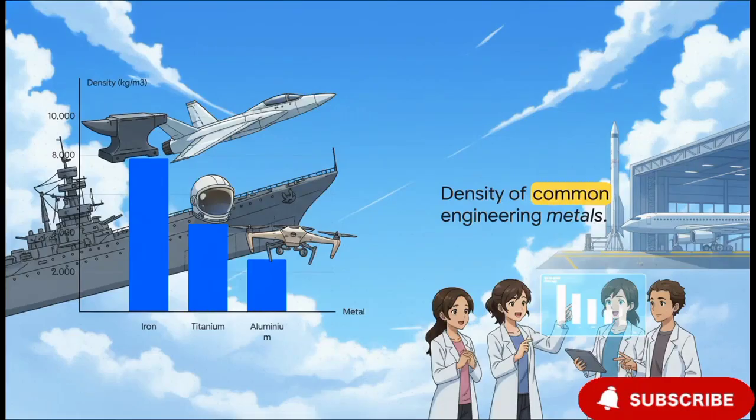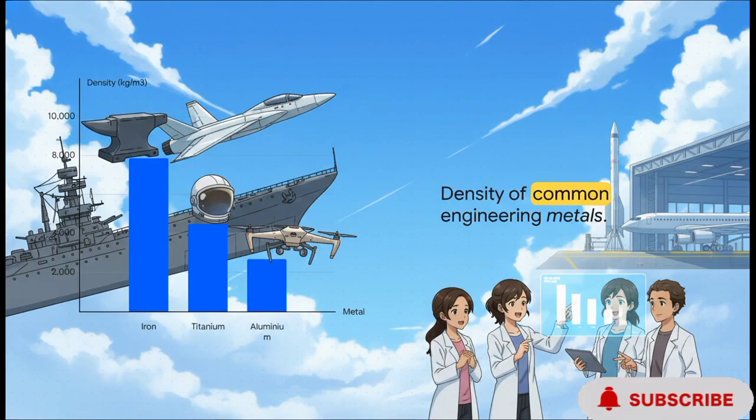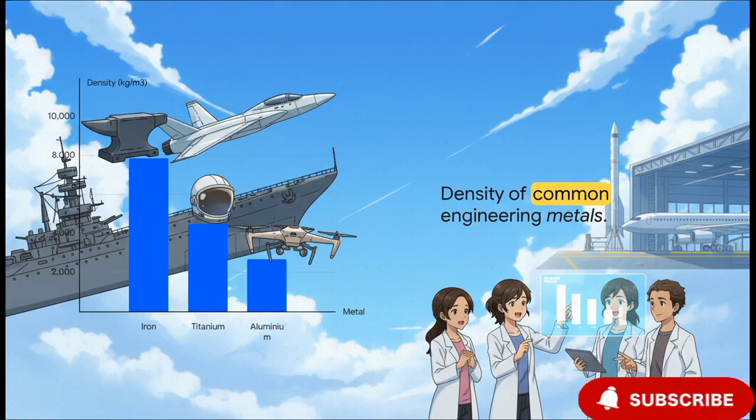Now, obviously, not all metals are created equal. Just think about the sheer difference in density for a second. Iron is incredibly dense, coming in at nearly 7,900 kilograms per cubic meter, but then you have titanium, which is almost half that weight, and aluminum, which is even lighter, at just 2,700. Visualizing this really builds an instant intuition for why aerospace engineers choose specific metals. I mean, you definitely wouldn't want to build an airplane out of solid iron. It would be way too heavy to ever get off the ground.